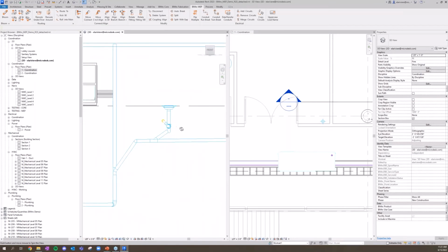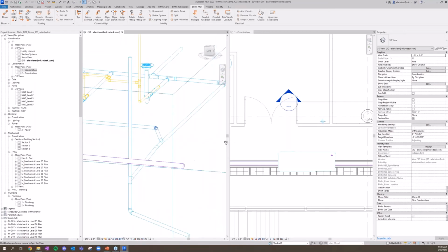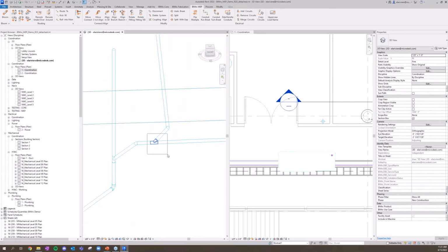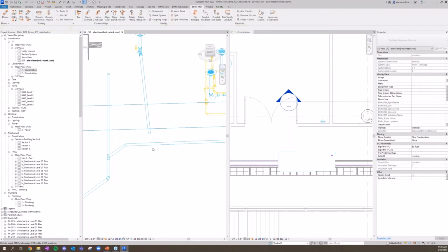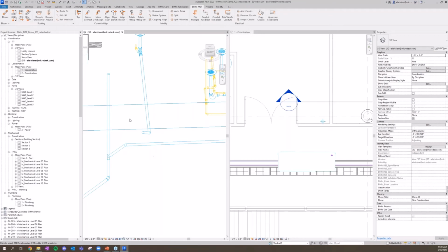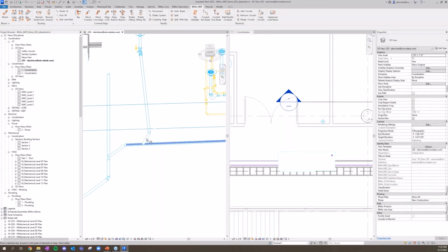And then similar to before, that's another align branch situation if you ask me. Using an align branch on the run there, we'll see it drop only in the vertical, allowing us to do another trim to corner. And we have a classic rolling offset. And for anyone else here who doesn't like that shape either, well, I've got one more for you. We can grab that chunk in the middle, rotate our fitting here, 45 degrees, or maybe we just want to elbow down at 45 degrees, whatever it may be. We can rotate those fittings around, line them up, and just use the trim extend command for that final connection after we have done that align branch.